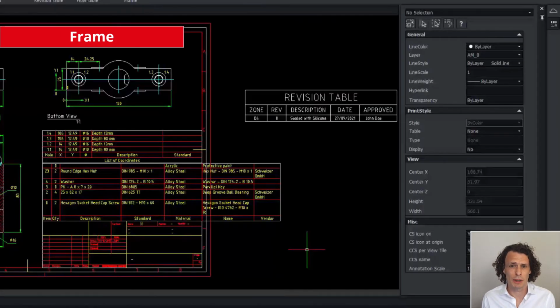After insertion of part lists, we now realize that our drawing doesn't fit in this frame anymore. So let's create a new frame with a larger paper size. Frames are also mechanical entities following the standard we are working on. The frame includes a title block with attributes that I can update.